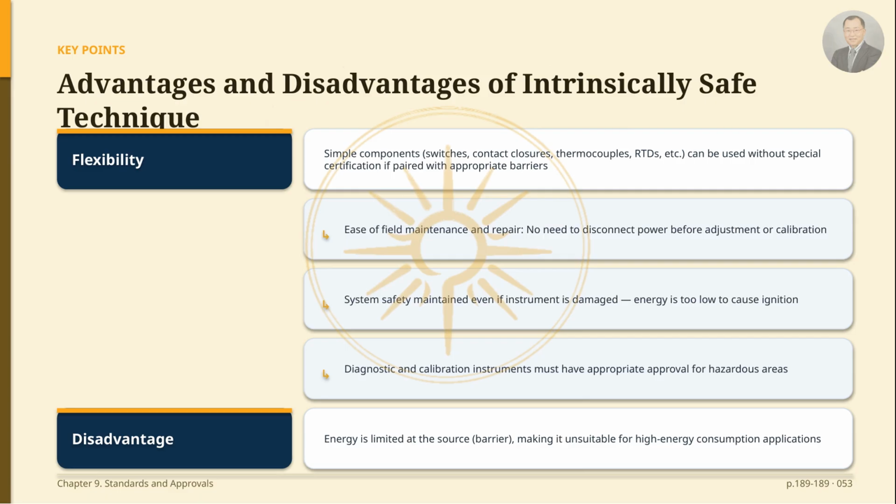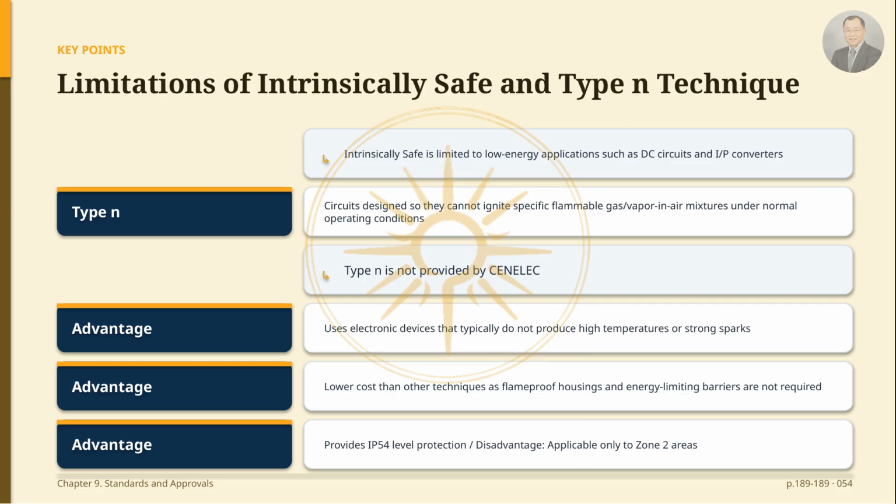There is also a disadvantage. Since energy is limited at the source or the barrier, this technique cannot be applied to high energy consumption applications. Intrinsic safety techniques are limited to low-energy applications, such as DC circuits and electro-pneumatic converters.